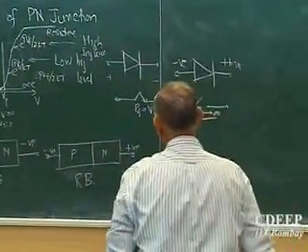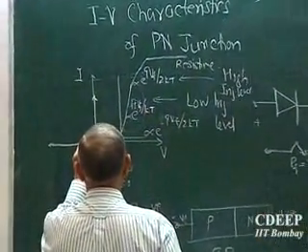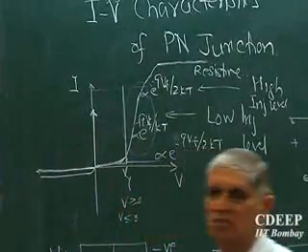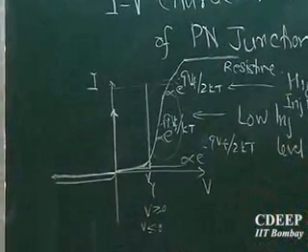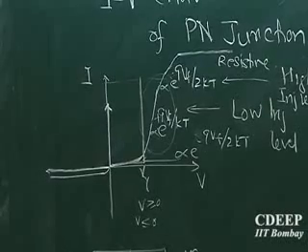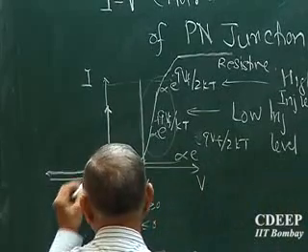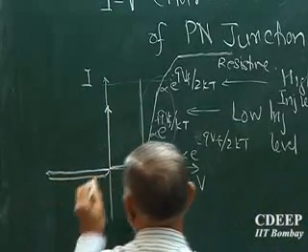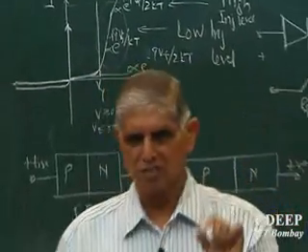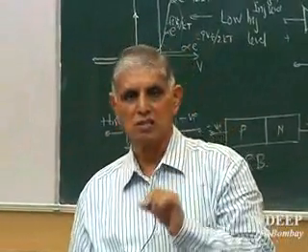If I apply reverse bias, I figure out by one theory that the current initially rises a bit and then remains constant. Whatever reverse bias voltage I apply, the current does not change. But in reality, what is the resistance if the device shows constant reverse current, very small but very constant current? What is the resistance I am talking about? Infinite, or a very large resistance.